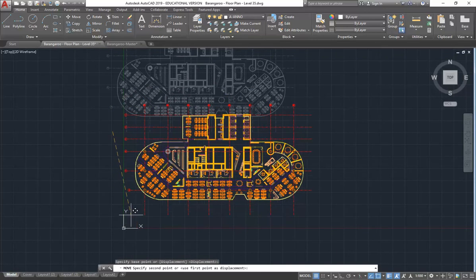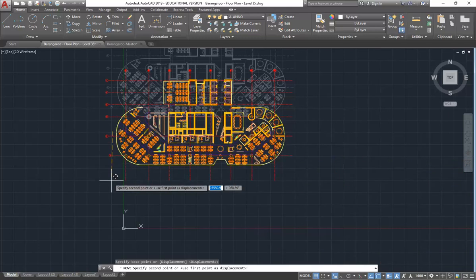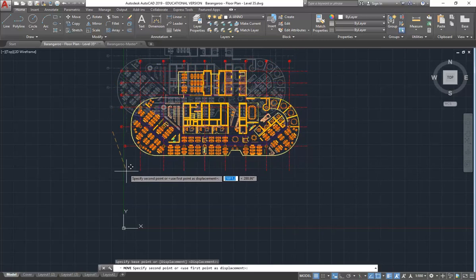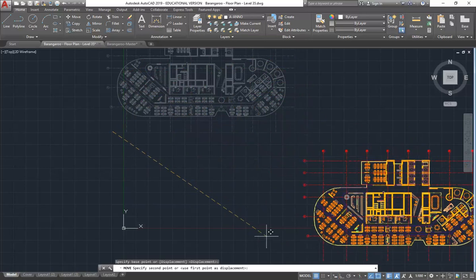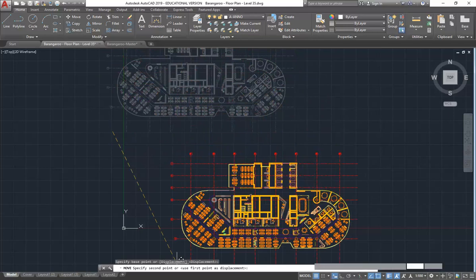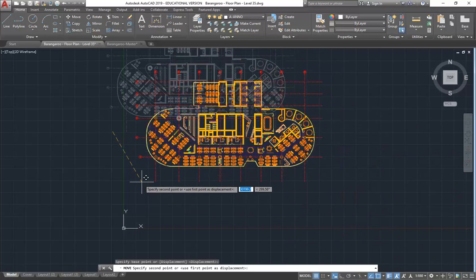You can, but if we type it in without doing anything else, it may not work because you've got to check that you've got this dynamic input option turned off. The way it works, you can see how the coordinates come up next to my cursor after I turn that option on. When it's off, they come up only down on the command line, but when you turn that on, the coordinates come up next to your cursor. So when that option's on, the coordinates are always relative, which means if I type 0,0, it's not going to move because it's measuring 0,0 from that point.